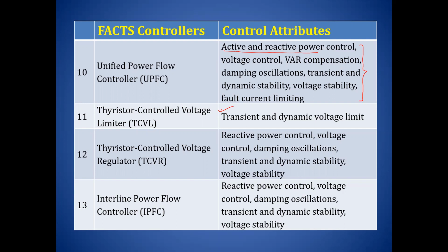So this transient voltage is going to die out with the help of nonlinear resistors, which may be called a metal oxide varistor. Due to this metal oxide varistor, under normal working voltage, it offers proper isolation between ground and line conductor, but during the transient condition, the overvoltage is safely grounded very well.